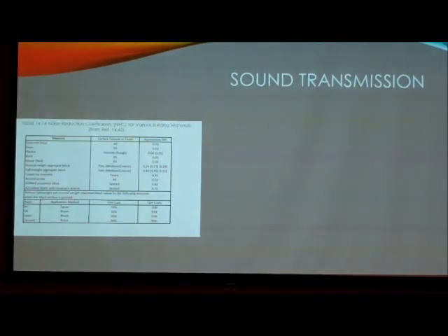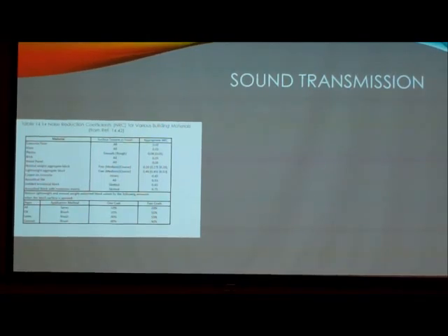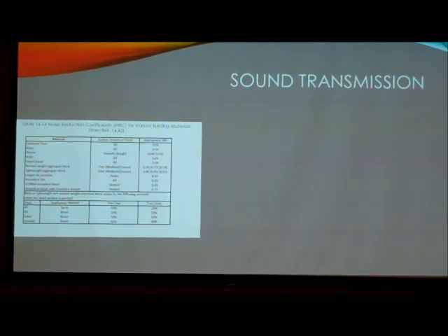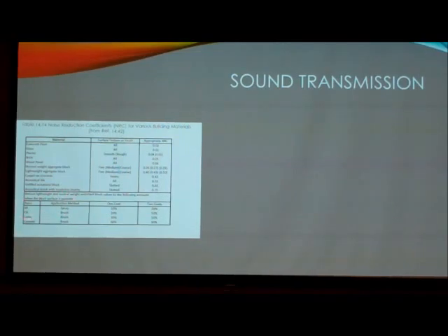So these are going to be your NRC values, or your noise reduction coefficients, that you're going to use when you're calculating different things. And this is a general one that I found over just various materials. So you have your concrete, your glass, plaster, brick, and all that stuff. What kind of texture finish it's going to be, and that's going to give you an appropriate coefficient. And then also, if you're planning on painting it or putting something else on the outside, it's going to tell you how many coats to apply for percentages that you want to increase your life by.